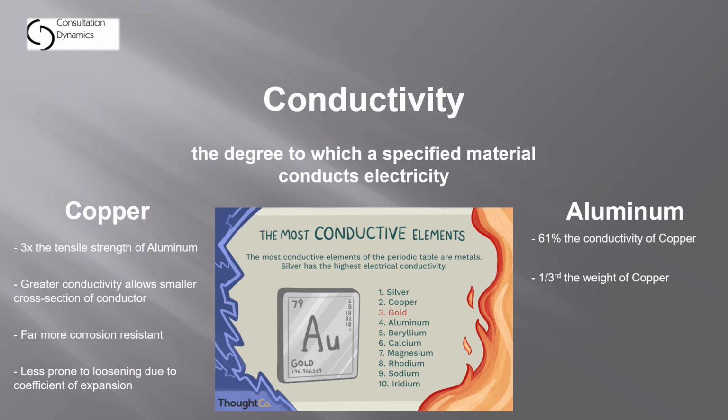And so, though it's less conductive when you compare the same copper size wire to the same aluminum size wire, aluminum is much lighter. Even if I went with a cross section twice the size of copper, it would still weigh less than the copper. As a result, we see aluminum wire used in a lot of high power transmission lines, because you can run great distances since it is much lighter, and still carry the necessary electricity without tremendous losses because you can increase the conductor size. In this way, the weight of the aluminum plays in its favor as a conductor in this particular type of application.